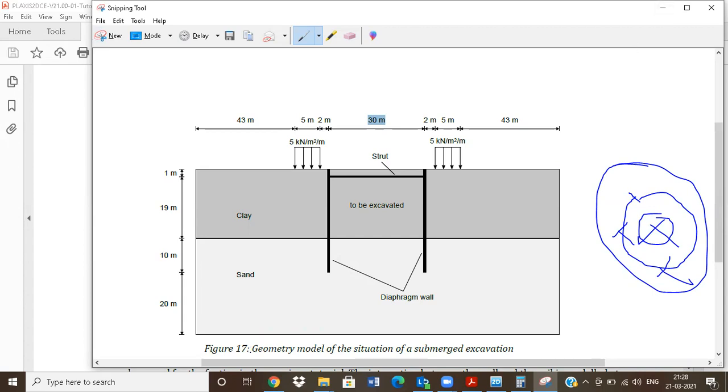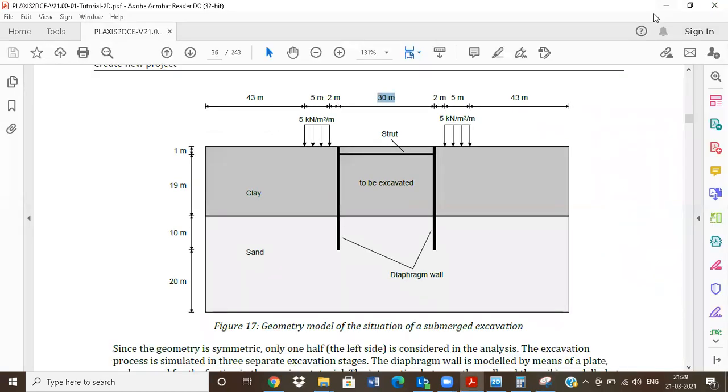Again, this is completely wrong because they have given only a single-place loading. They clearly mention the geometry of a model for submerged excavations, and they never mentioned a diameter. So this is to be a plane strain model. Also, loading the whole circle at a time is not possible. There is no machine that can do such operations, so it is unrealistic. By considering these two, I am considering this a plane strain model.